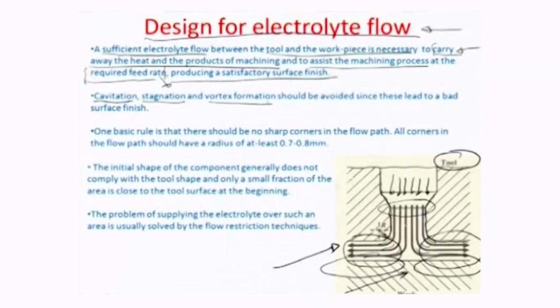You have seen that in USM case this cavitation happens because of the vibrating tool head at a very high frequency. So, the fluid can no longer follow that tool head, and there are thousands and thousands of bubbles which are created because of that, because the air typically bleeds out and fulfills the gap done by that vibrating tool head. In the ECM case, the same bubble is generated electrochemically, okay, by the system. So, then there can be a possibility of stagnation of the flows. Okay. So, it is a creepy flow, it is a laminar flow.